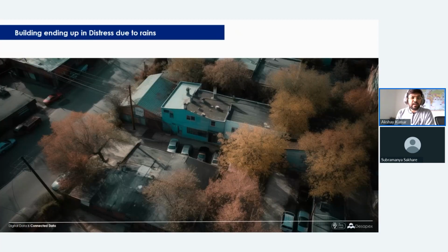So what happens when there is a lot of rain deposition? The consequence of rain deposition can be quite distressing because it manifests as unsightly stains. This leads to troublesome leaks and even dimension alterations. These detrimental effects of water penetrating through the cladding can also extend inward, leading to similar issues within the walls. And this can cause extensive wetting.